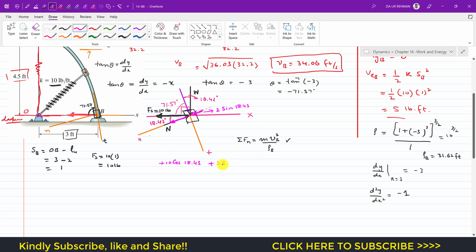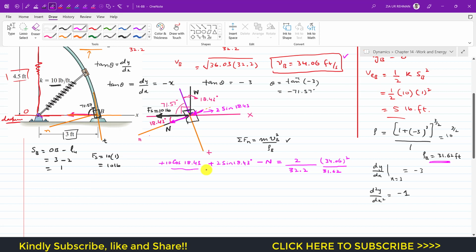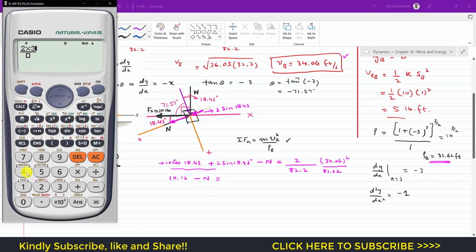So we will write plus 2 sine of 18.43 degrees, and this n is acting in the negative n direction, so we will write minus n, and this is equal to the mass, which is 2 pound weight divided by g value, 32.2, times Vb squared, Vb is known, 34.06 squared, divided by the radius of curvature at B, which is 31.62. So 10 cos of 18.43 plus 2 sine of 18.43 gives us 10.12. From this we get 10.12 minus n, equal to 2 multiplied by 34.06 squared divided by 32.2 multiplied by 31.62. This gives us 2.278, which is approximately 2.28.